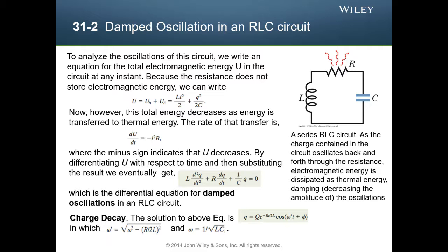And then we write the loop equation, so we have LC V double dot plus RC V dot plus V equals Vs. We have a second order ODE like this, or you can normalize it like this: V double dot plus R over L V dot plus 1 over LC V equals Vs over LC.